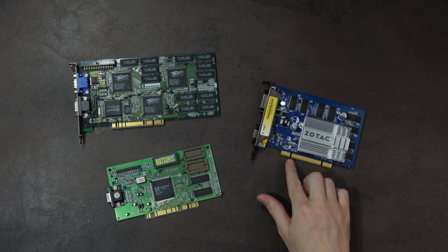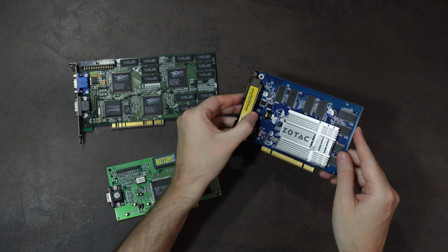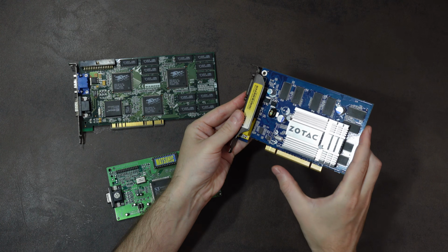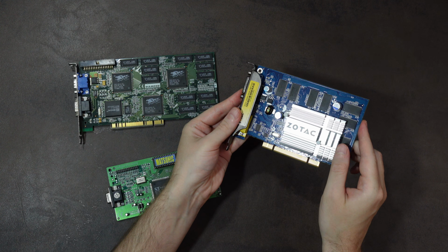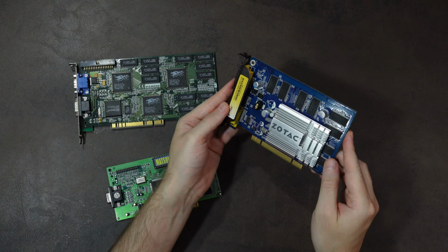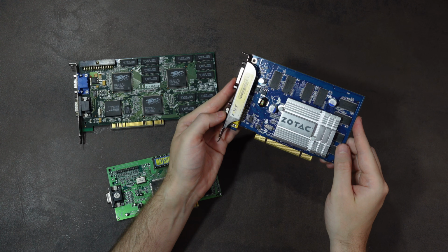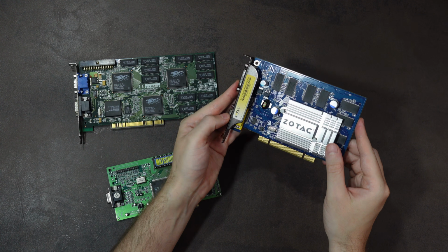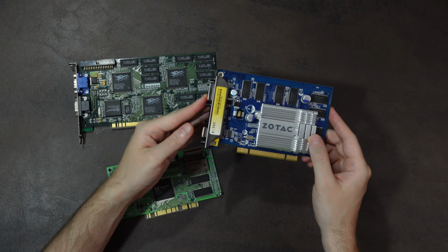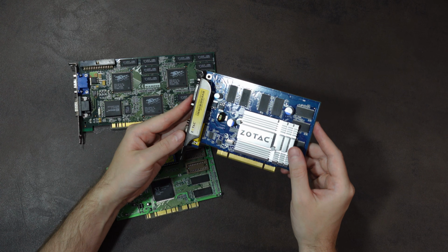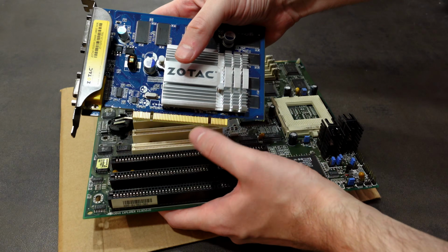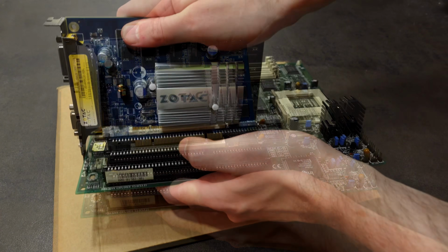It gets problematic when it comes to cards with a universal connection, which have a notch in the back and in the front, but then are not so universal in their inner workings and need 3.3V to operate. This can very well happen with newer graphics cards. For example, this GeForce FX 5200 from Zotac from 2003. This card fits in old boards physically, but will not work there.